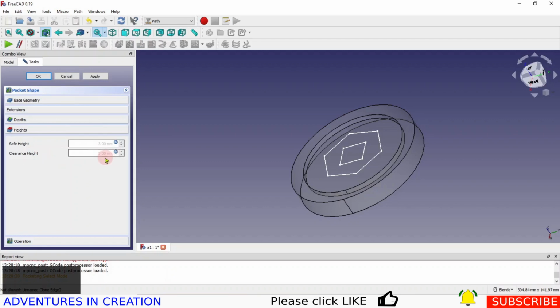So my clearance height is 5mm. That means if the cutter is 5mm above, it can wrap it. And 3mm above is a safe height. It's not going to hit anything at that height.